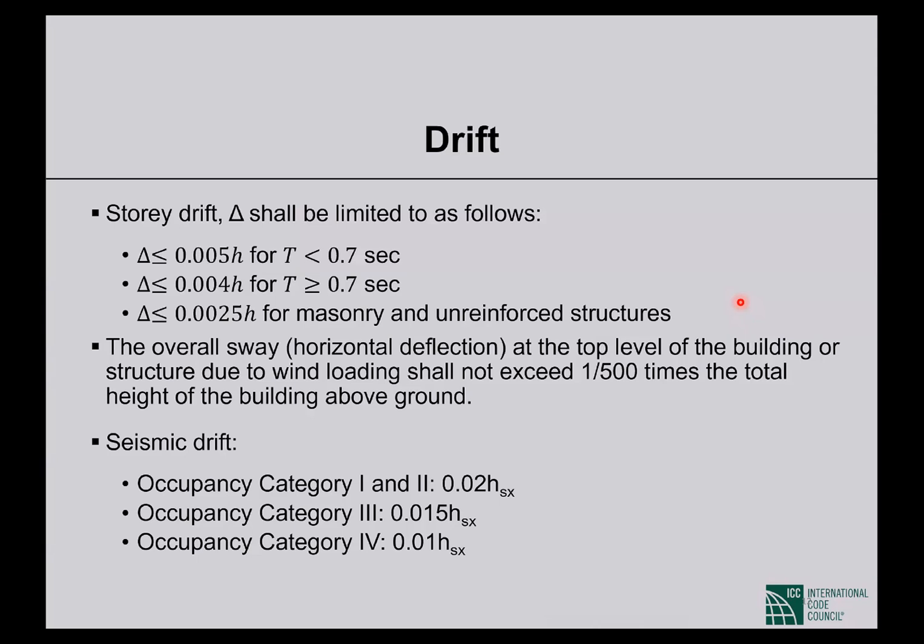Then the time it takes to come back to its original position or to make one cycle is called the period of that structure. Very simply, if I pull a structure in one direction and remove the force and make it free, it vibrates freely without any force, and it goes to the other direction because of vibration and comes back, and the time that is required to make one cycle is called the period of the structure.